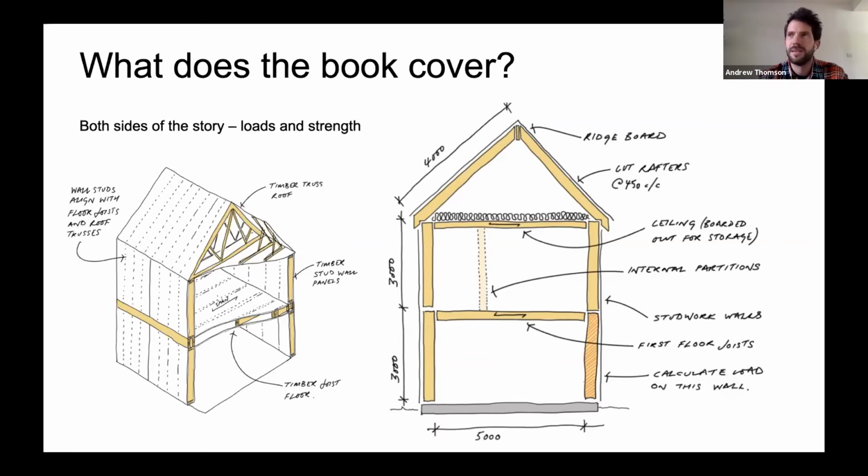useless, because anyone who's taught in a university or whatever may well have marked a piece of work where the method for sizing a beam is perfect, but the beam has come out as 50 mil by 20 mil because the load is minimal, or the opposite, it's a meter deep. So we have tried, specifically for timber buildings, to explain how you can calculate the loads on elements, because it's a really important part of the design process.